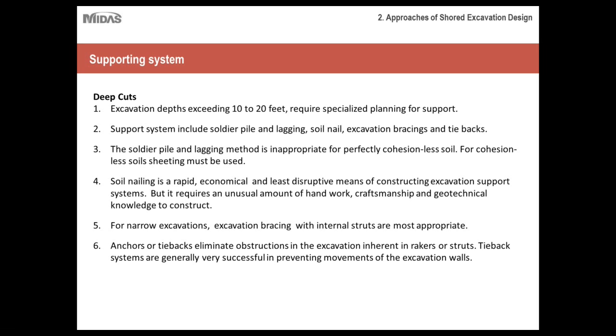Then another way of providing the support, and a very popular one, is anchors or tiebacks. Now the advantage of using anchors and tiebacks is that they eliminate any kind of obstruction in the excavation, and if you are applying struts to open excavation sites, then you are actually limiting your work scope and causing obstruction.